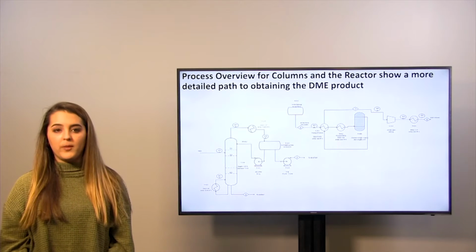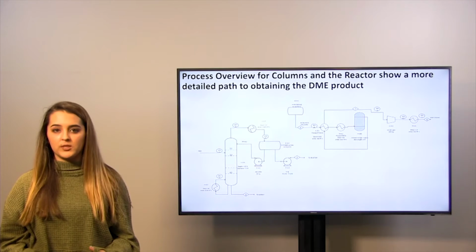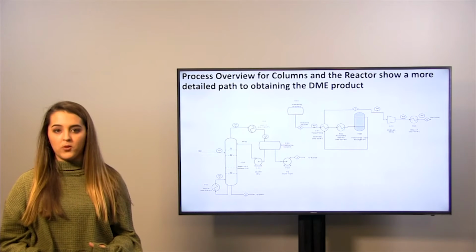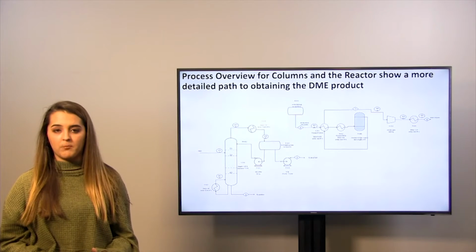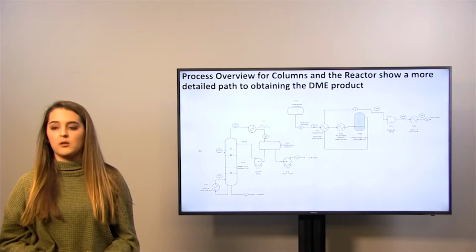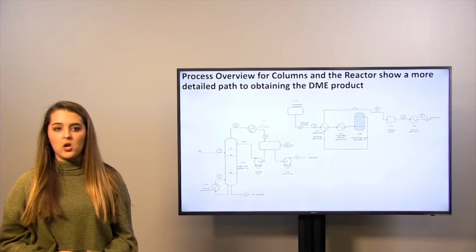We came across two main problems throughout our project. The first is that it's hard to store DME because it has such a low boiling point that to store it in the liquid phase, it needs to be at an extremely high pressure and low temperature, which is very costly to our system.